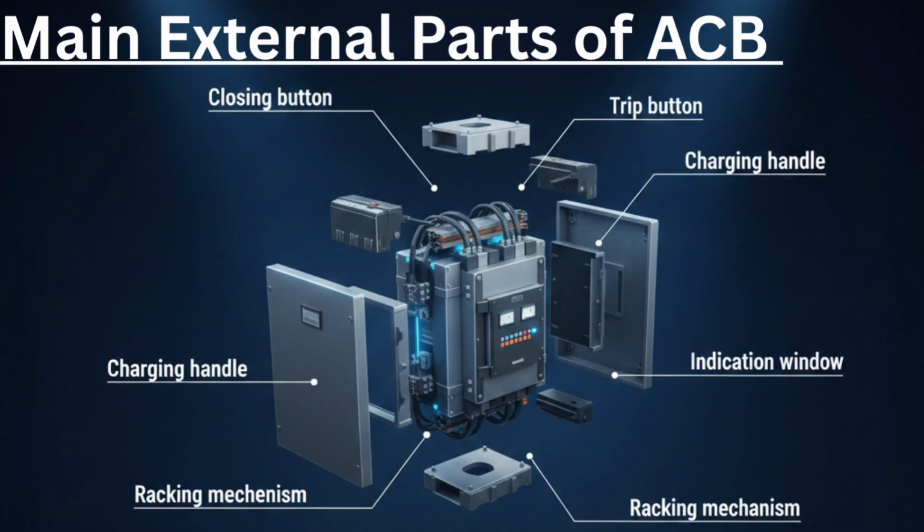Main external parts of ACB. On this slide, you see the external view of the air circuit breaker. Let us understand each visible part. Closing button, used to close the breaker manually. Trip button, used to open the breaker manually. Charging handle, used to manually charge the closing spring. Indication window shows breaker status: on, off, tripped. Terminal connections, where power cables connect. Racking mechanism, used in draw-out type ACB to move the breaker from service to test or isolated position.